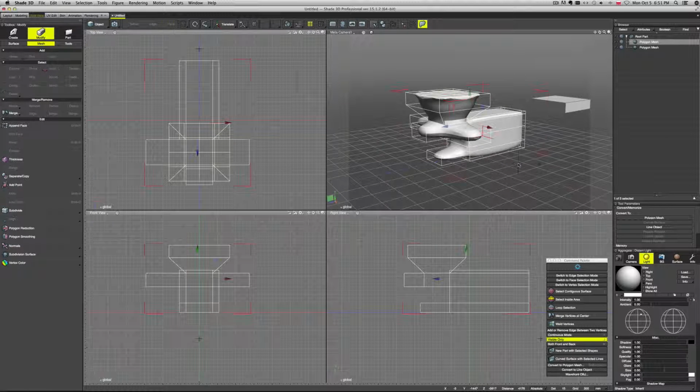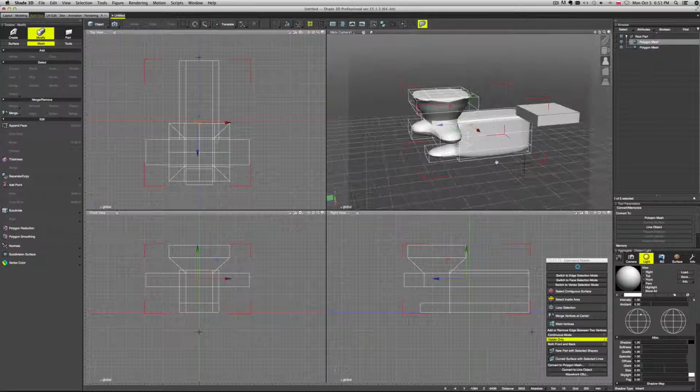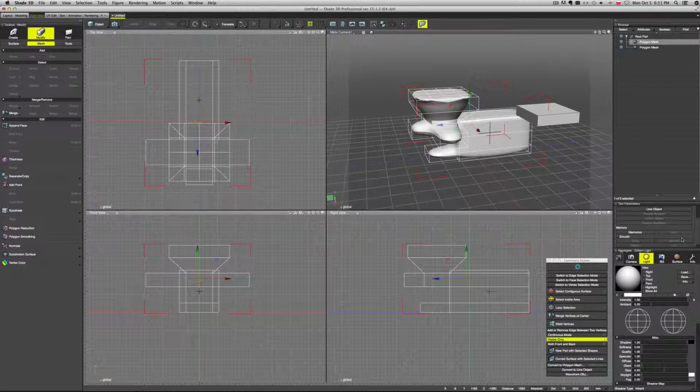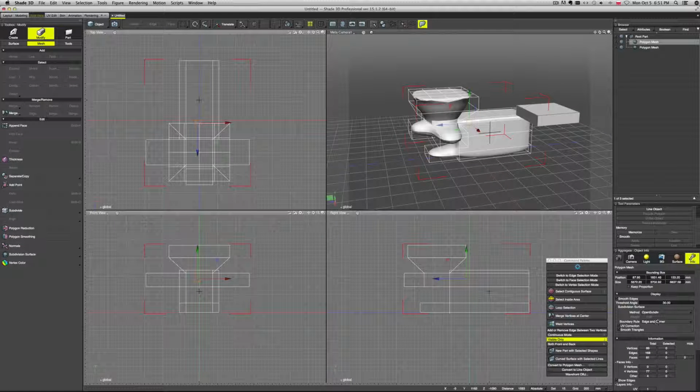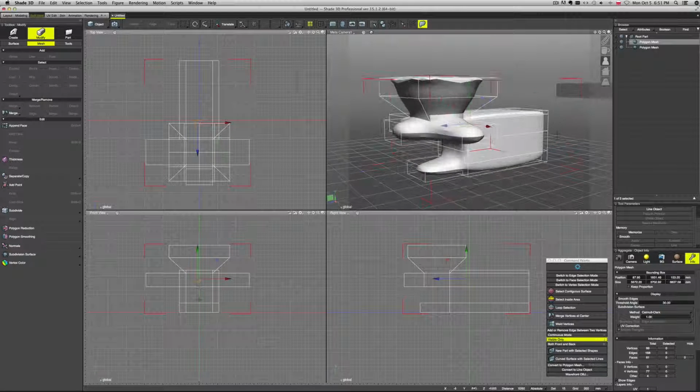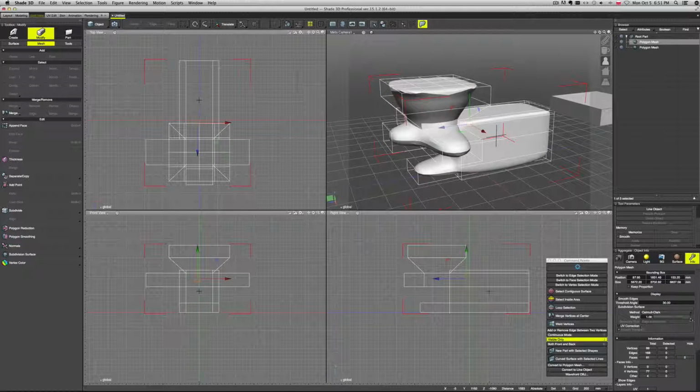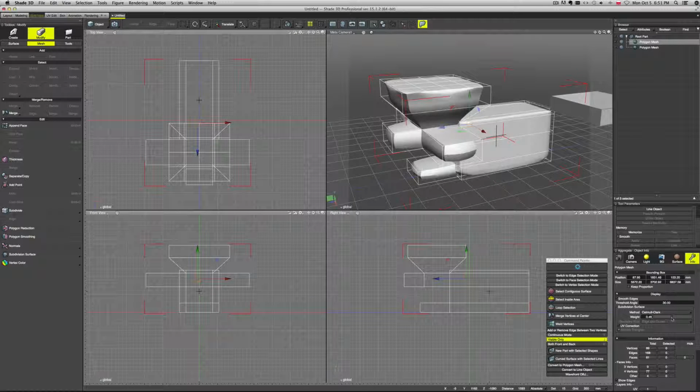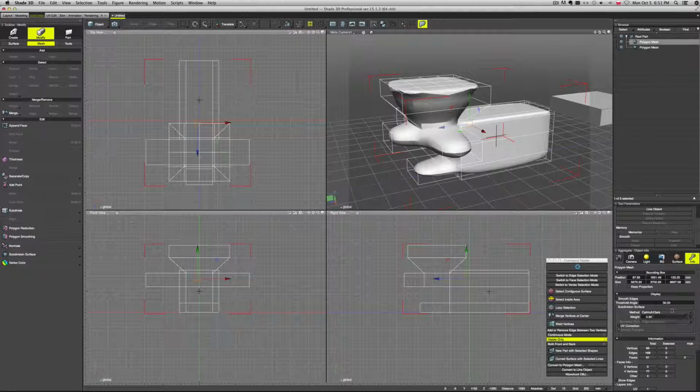And if you turn on this preview of subdivision, you can go to the info tab, and here you can change the method. There are 3 different methods, and each of them gives slightly different results. Some of them you can tweak, like this one, for instance. You can change the weight, so basically the degree of this subdivision.